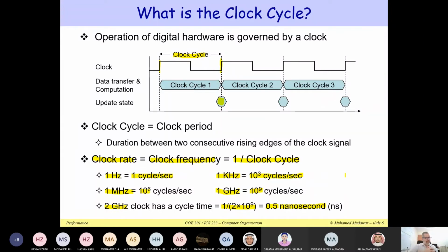You will see that by increasing the clock frequency, we can reduce the execution time. This is what the CPU does. If the CPU is running many instructions and would like to speed up the execution of the program, to reduce the execution time, then it will increase the clock frequency dynamically.